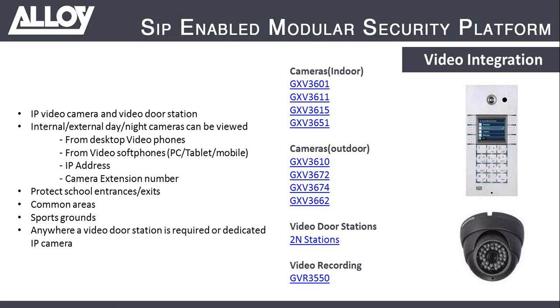And on top of that, the final piece of that puzzle is the video recording. Now, there's a device from Grandstream called the GVR 3550, and it is low cost but a very sophisticated NVR for network recording of video data from these cameras. It can take a large number of data feeds. It can record all of them. It will support up to 16 terabytes of storage. And then you have an option for it what you do when that capacity becomes full. So override, stop recording, etc., and alarm when that issue arises as well.